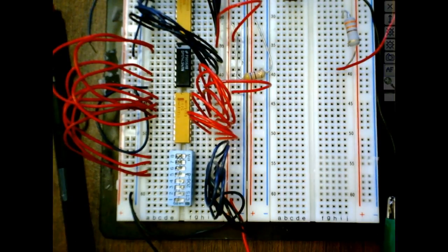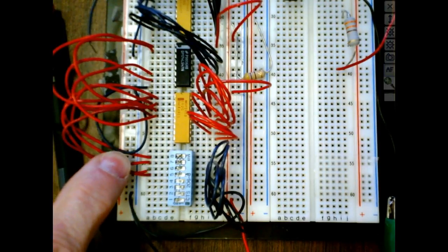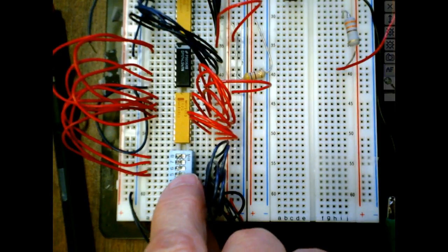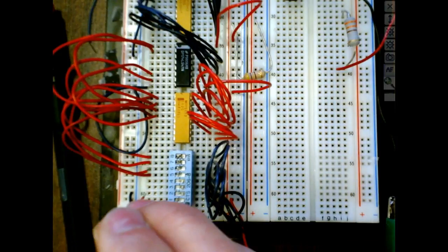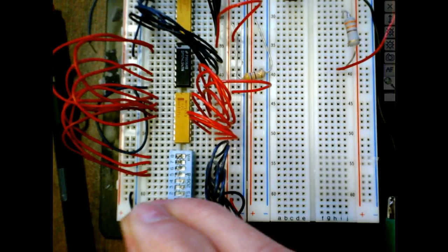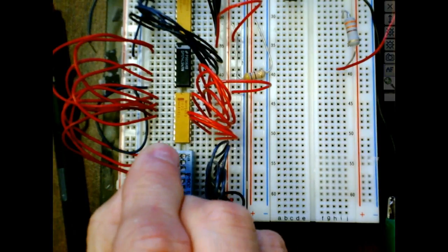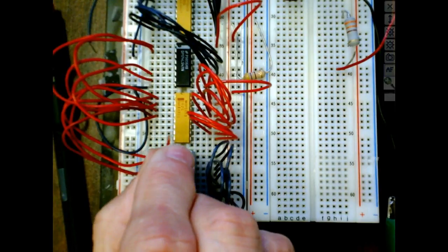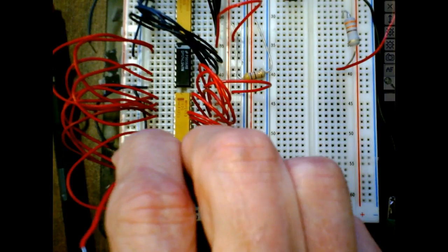Let's go back to the schematic. So here's my ABCD inputs right here, and we're using switch 8, 7, 6, and 5. Then I'm supposed to hook up my lamp test. What's the lamp test on the 7447? Okay, so I'm going to bring it over to a pull-up resistor, and then I'm going to run a jumper over to 3.